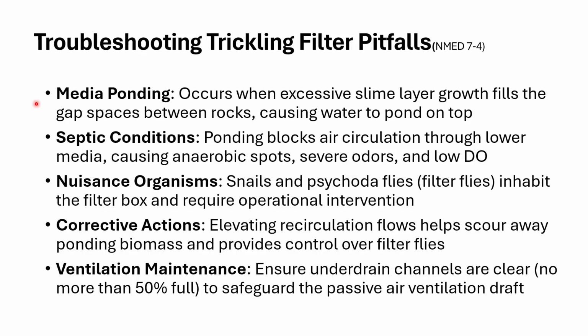You can have what's called media ponding. And what happens with media ponding, that slime layer that we talked about, it starts filling the voids between the rocks and it doesn't slough off. It doesn't fall off and fall down to maintain those voids. It's like you're clogging up your filter. You got a clogged nose or something. Nothing's going to pass through, or portions of the incoming influent off the primary clarifier, they're just going to pond up because those snot layers, that slime layer, is clogging up the voids.